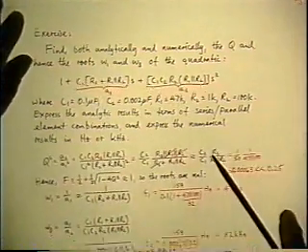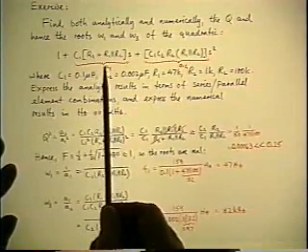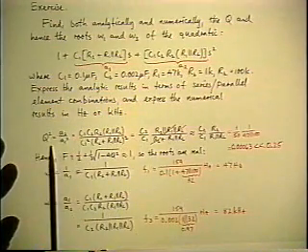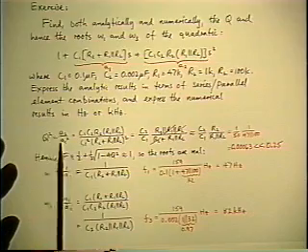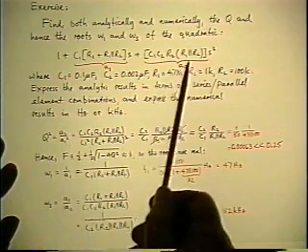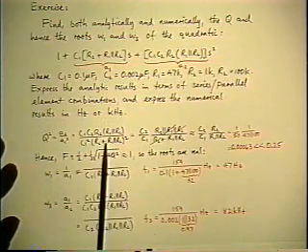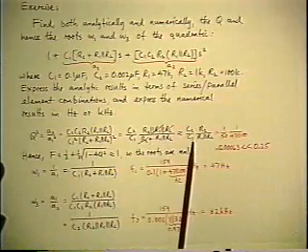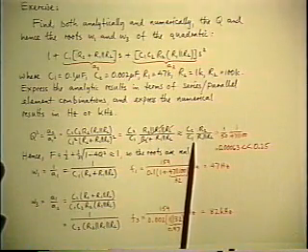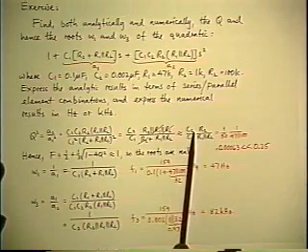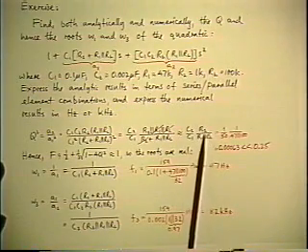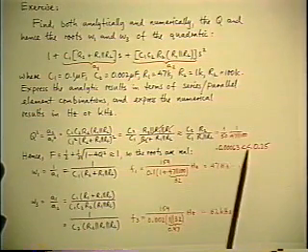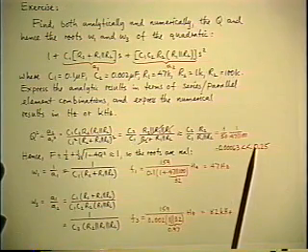So the approach from now on is these coefficients represent the A1 and the A2 in the version that we've just had. So the first thing you do is find out what the value of the Q is. So here's the definition of Q. Q squared is A2 over A1 squared, which you get this. And you can in fact reduce it very simply, although you don't even have to go that far. And you see immediately that because C1 is 50 times bigger than C2, and R1 parallel RL is a lot bigger than R2, then Q squared is indeed very small, and Q is much less than 0.5.